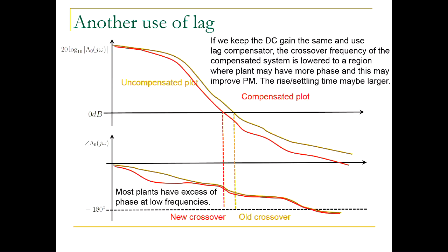What is a disadvantage of this technique? We talked about this last lecture. So moving crossover frequency to be smaller, how does that affect the response, step response, let's say? Sorry? I didn't hear you. Bandwidth, yes. So the bandwidth would be reduced. That's right. What else?